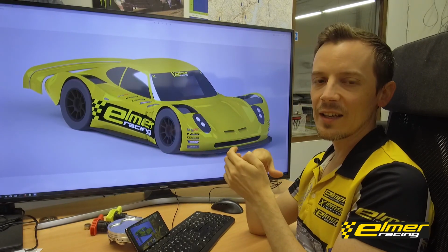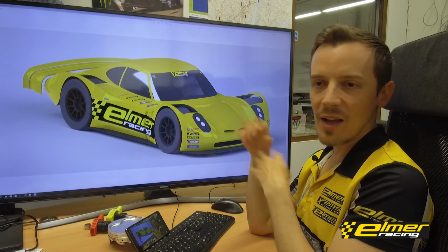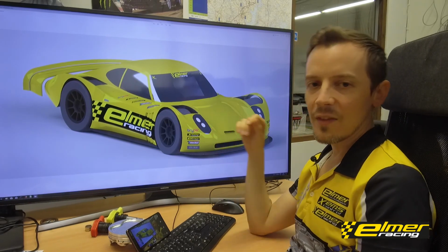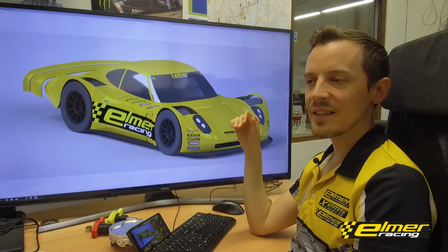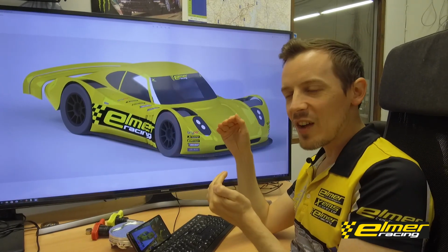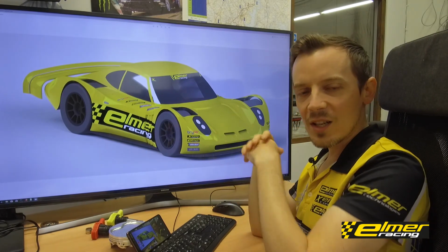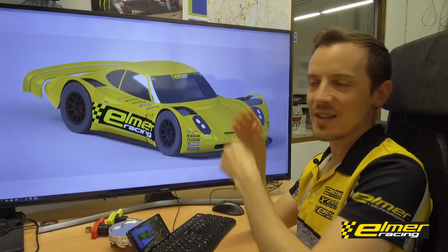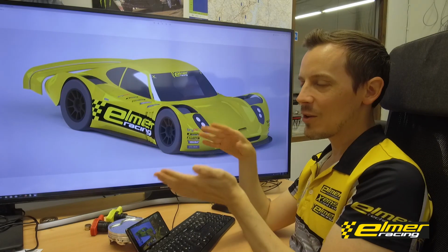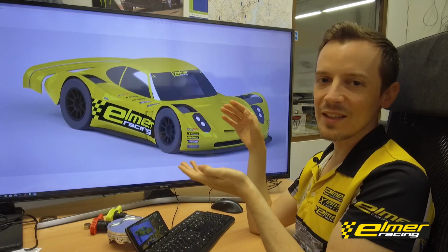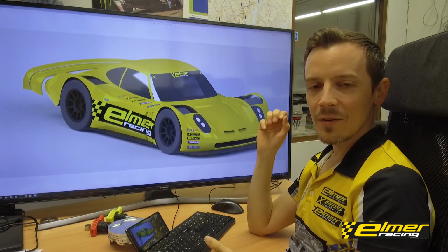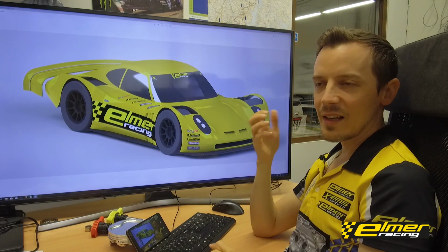Even if you know what you're doing, it's very easy to get results that have absolutely nothing to do with real world scenarios, because a tiny difference somewhere can make the whole flow field completely different. It's not like, okay, we're within 5% or something. If you have a tiny error somewhere that creates a completely different flow field, then you can be off by 70% or something, and then making a change in the model will not correlate with the real world at all, because your whole flow field is completely different to what it would be in the real world. So those are things to think about, but it's not anything that is super difficult.